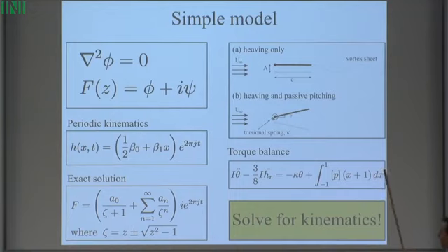This theory compares pretty well to experiments, as I showed you, and other simulations. I've benchmarked it against vortex methods that do take into account vortex sheet rollup. And as far as how the wing moves, the performance of the wing, it captures all of that pretty accurately. So that might be suggesting that vortex sheet rollup, since it happens downstream, is not directly affecting the wing's motion as much. Again, I can't quantify that, but it's something I want to look into more.